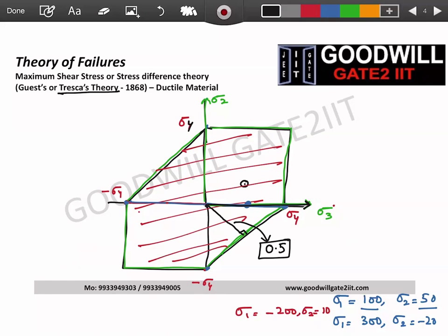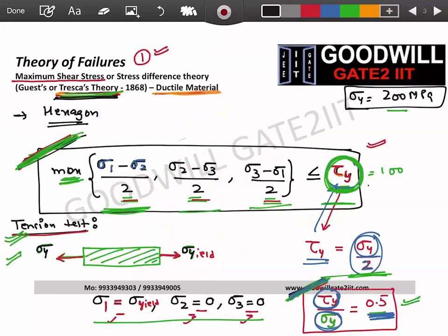If you recall basic elasticity, correct, right? If your principal plane is theta, then your maximum shear stress plane is theta plus 45 degrees. Correct? And now, magnitude wise, if your principal stress is this much, what is your shear stress? It is half, right? That's what your relation is saying. If your principal stresses are something, then your shear stress is half of it.